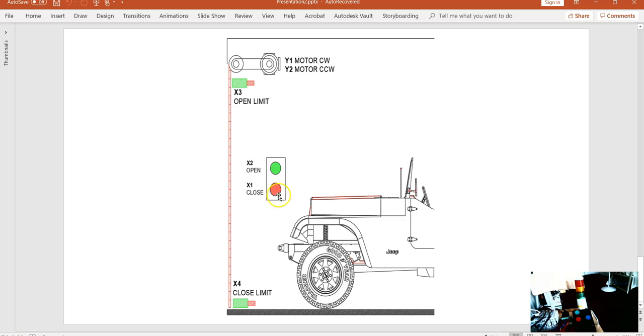We'll have visualization for our buttons and for our open limits and closed limits. And because we have the HMI, when we initially did this, we ran into problems where we've always had problems where we don't have enough push buttons. On our control panel we have a start, we have a stop, and we have a reset, and we're kind of limited with 3. When we go to the HMI, instead of this being an X bit, we can wire that into a C bit, and we can simulate the function.